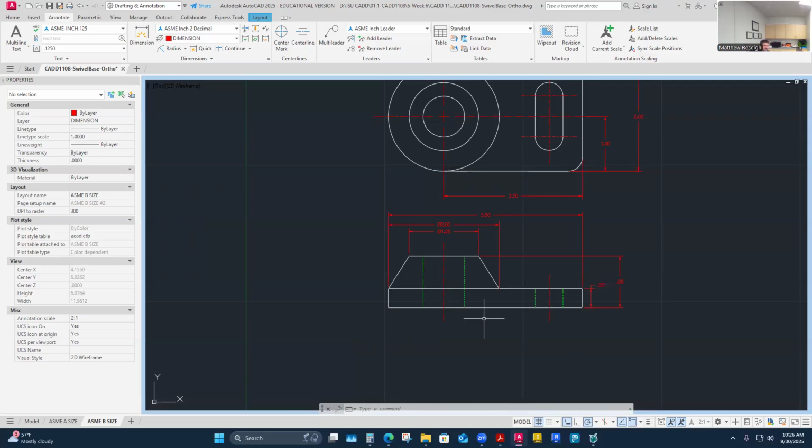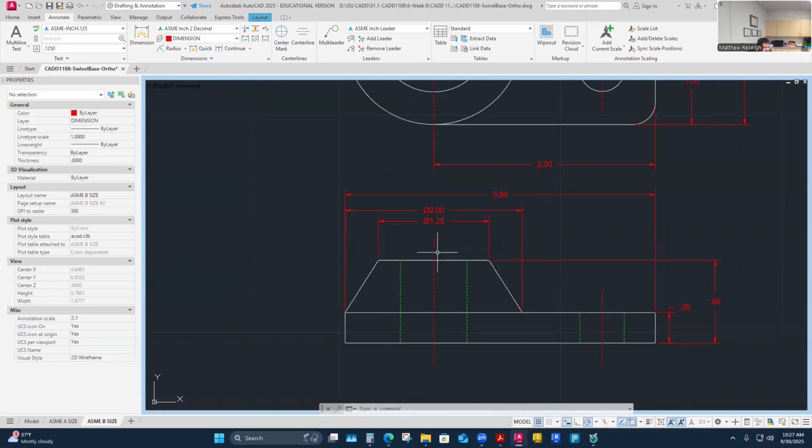especially if the bore center hole or the concentric nature of all those features are going to be pulled as a datum, then I kind of have those. I would kind of control the horizontal and vertical nature of that crosshair as maybe two datums. And if that's the case, then I definitely have the dimensioning I need for locating potentially. It's arguable that I could do a linear dimension from center out to there and from center out to there, and that locates it in relation that it is concentric. And we've been doing that a little bit. That's good locating. From the center, I'm controlling out to the